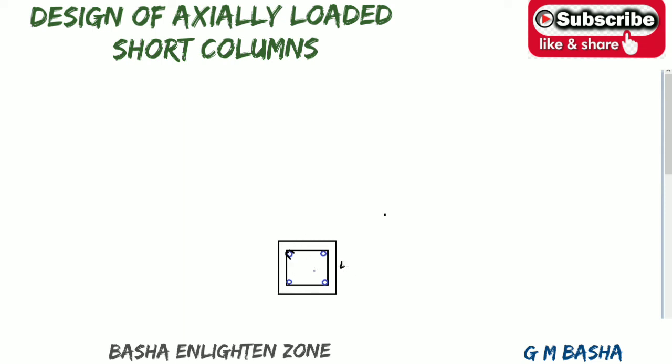Then these are the dimensions of the column, which is 420 by 420, and we are providing a minimum cover of 40 and 40 here. Here I am mentioning that it is 4 bars of 25 dia. So this is the cross section of the square column.